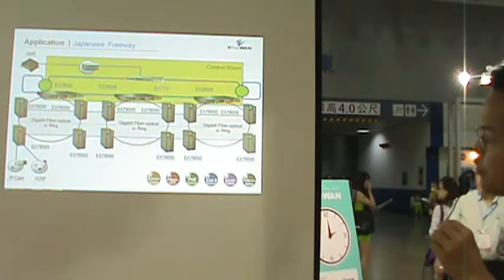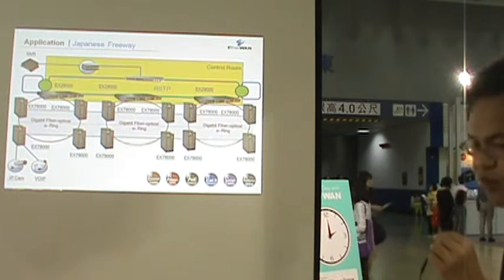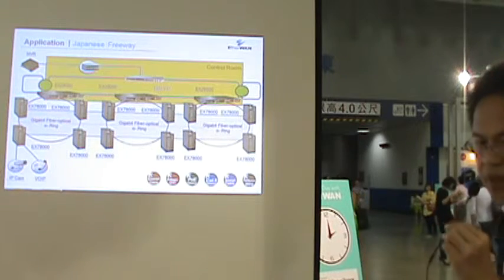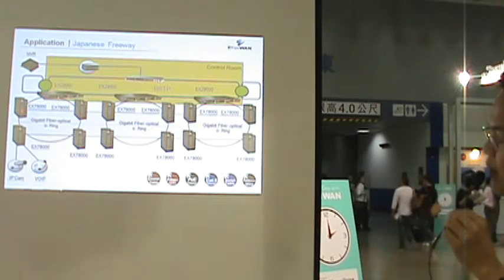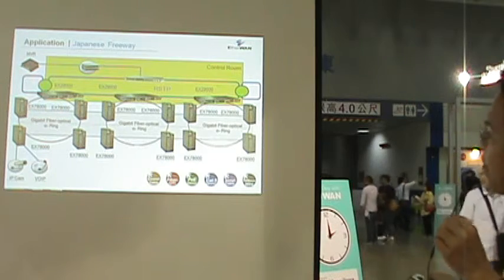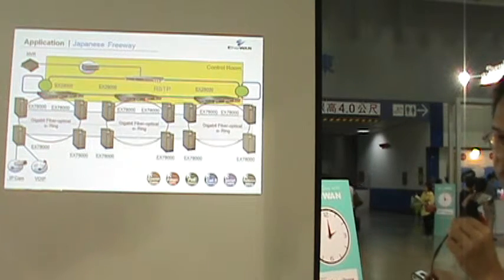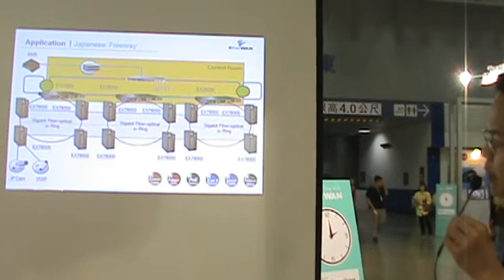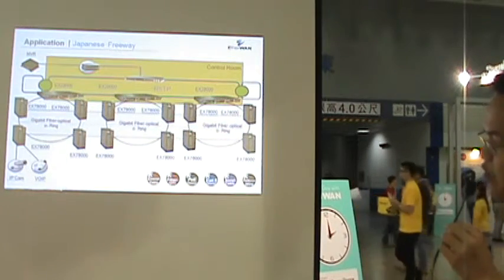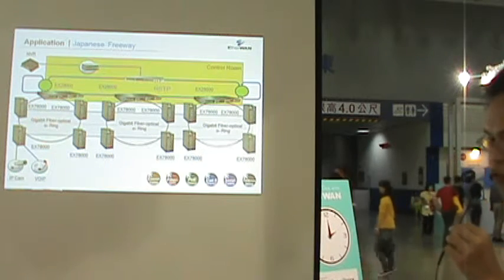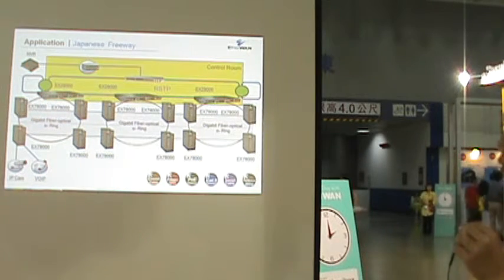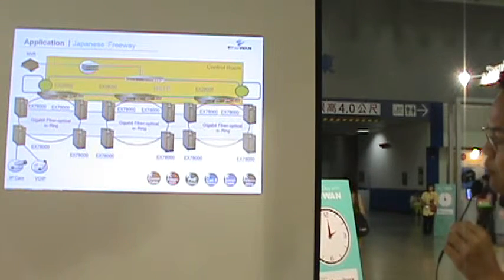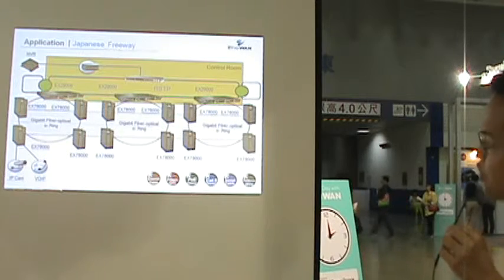We also suggest they configure Turbo Ring. The reason to use Turbo Ring redundancy is that it has 15 milliseconds of recovery time, compared to the traditional rapid spanning tree, which takes about 3 to 5 seconds. It's much faster, because applications like camera view or voice over IP are critical applications. So normally we require fast recovery in order to handle this type of application.